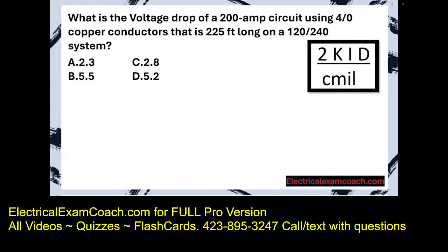I like to physically write it down on the piece of paper so I can go through one step at a time. Then I'm going to draw a large division line so I can put my inputs on top and then go look for my C mils. Let's start with 2. Is this a single phase or a 3-phase service? Well, this one is single phase, so it is going to be 2.